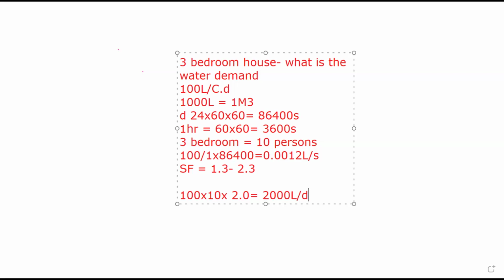And that is why when we come to that module, if you are designing for storm, you must ask yourself, is it a 10-year return period rain? Is it a 20-year rain? Is it a 25-year rain? Because the designer who does the design with a 50-year rain and the one who does with 10-year rain, this one might get 2 billion, this one will get 4 billion. Then suddenly the governor will say your design is expensive, without knowing that you have used a safety factor of a 50-year storm.